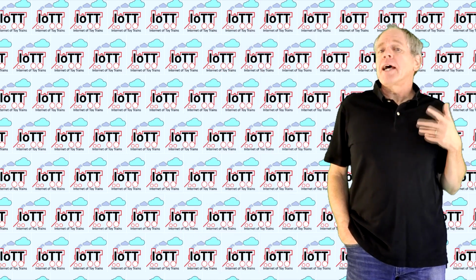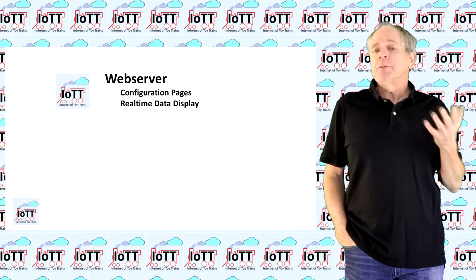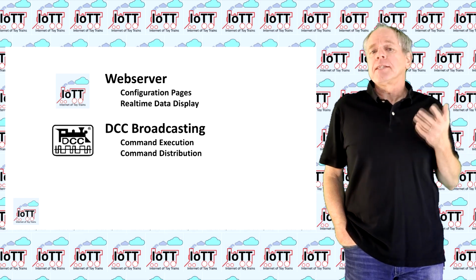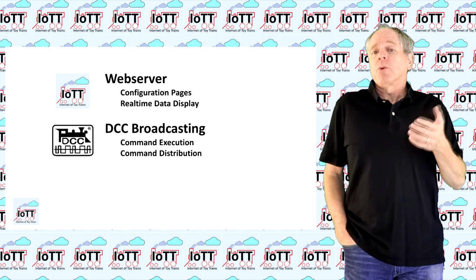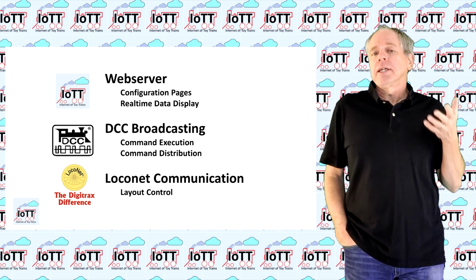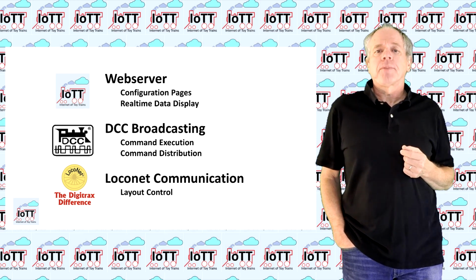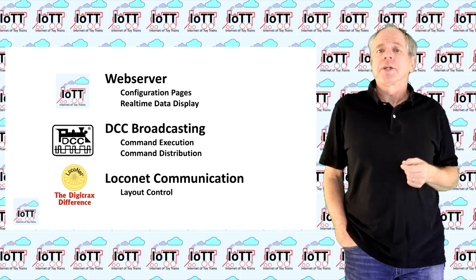The IoTT Stick has three groups of communication functions. First, it acts as web server for the various pages designed to configure and operate the IoTT Stick. Then it can receive DCC track information from the layout, process it to a function head and also broadcast it to other receivers. And third, it acts as a node in a Loconet layout control network, can receive information, process it and distribute the results. Let's have a closer look into these functions, what they do and how they work.